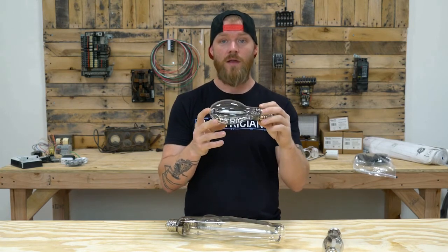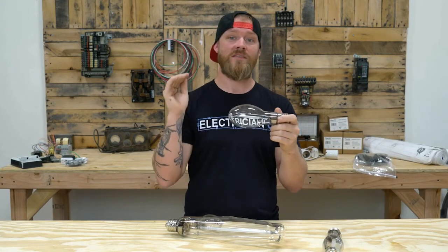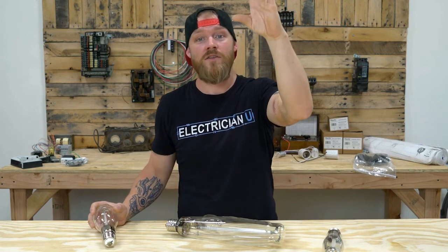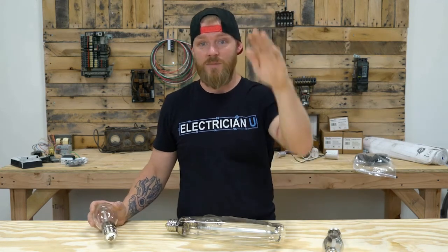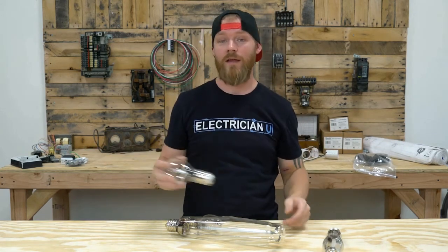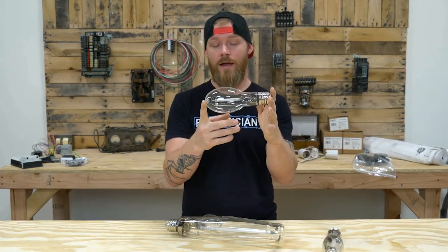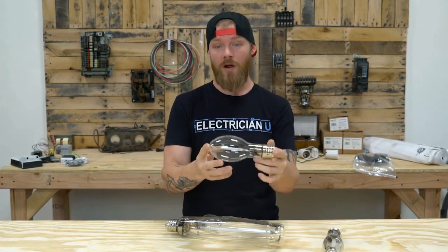High pressure sodium, you can tell when the lamps are starting to fail because they cycle on and off. If you stand in a parking lot for 30 minutes and watch one of these lamps, it'll shut off and be off for 10, 15 minutes, and then it'll start to ignite again, and it'll get up to pretty close to full bright, and it might even stay there for a minute or two, and then it shuts off again. And it just keeps doing that over and over, where a metal halide's not going to do that. So that's how you can diagnose whether or not a high pressure sodium lamp is your problem.